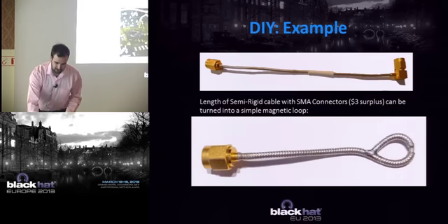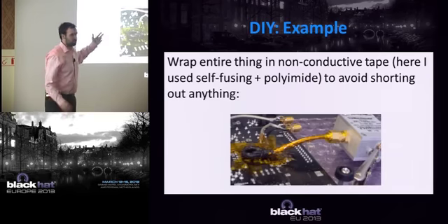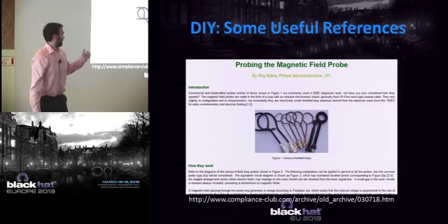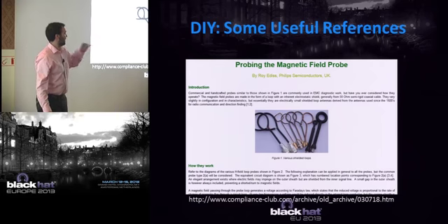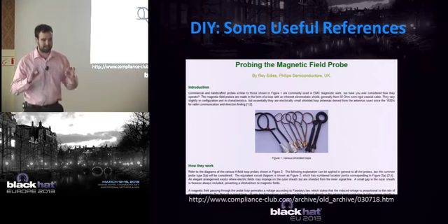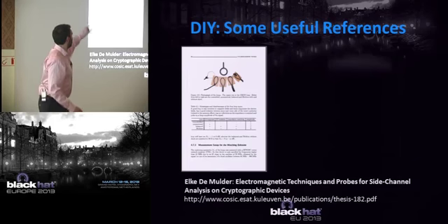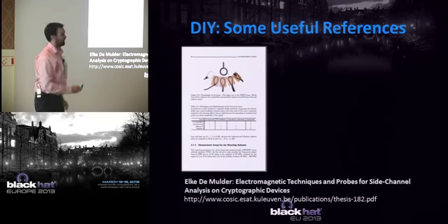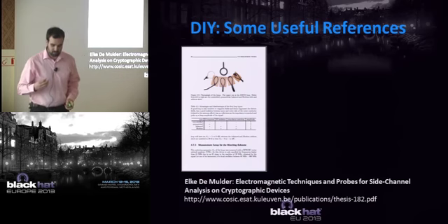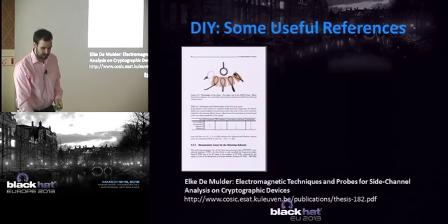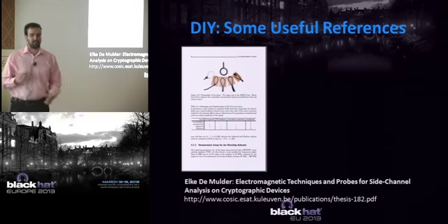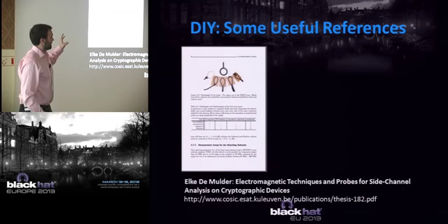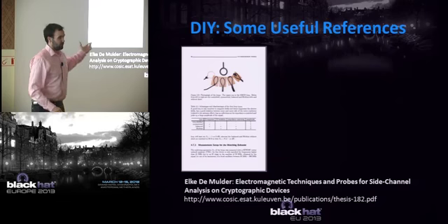I've had some demos of showing this, and it achieves pretty much similar results to what you'd expect. There are a few good papers of a guy making a whole bunch of these. He's using them for a different purpose, but it's the exact same thing. And there's even someone who's done a thesis on making his own magnetic field probes and testing them for different characteristics. So there's a lot of great DIY references. And this is, again, a little cooler because you can do this without having to physically modify a real device. So when you're attacking something that isn't just a board you're making, you may want to use an EM probe instead.